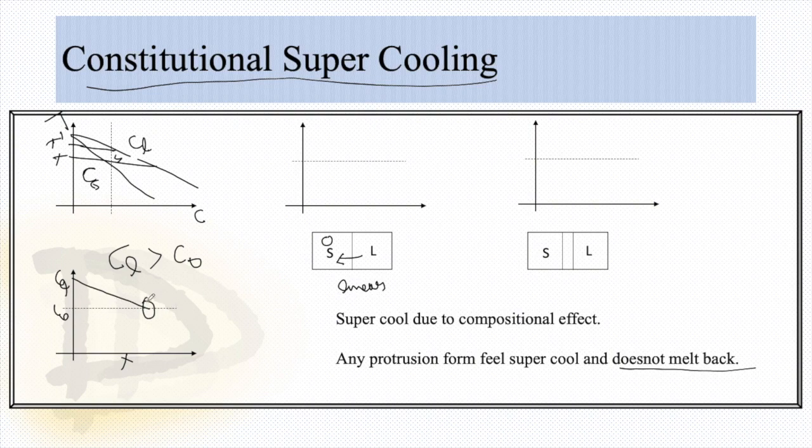The average composition is equivalent to the liquid composition as we measured, but actually at the interface, the liquid composition is greater than the average composition we measure. If we measure the temperature at T prime, we get the liquidus line while calculating. The line would be this, but the actual line will go steeply away from the liquidus line.